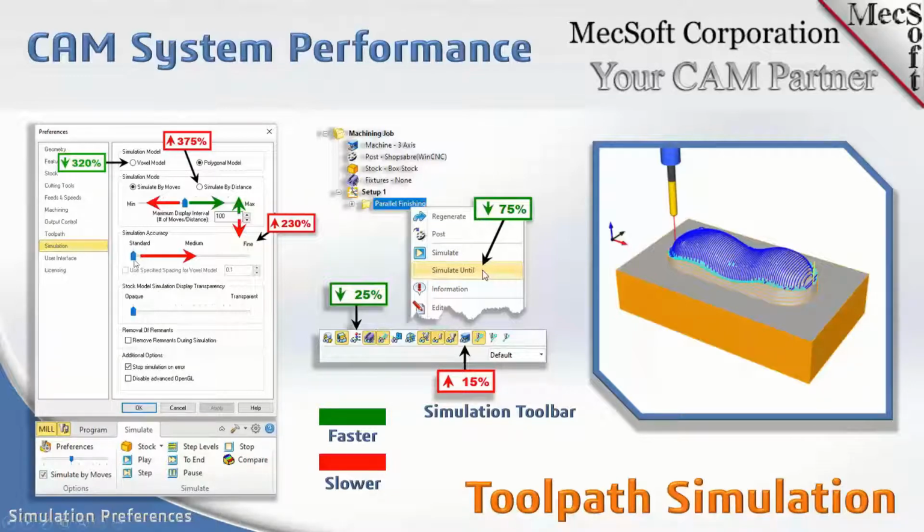Again, there's a slider for accuracy: standard, medium, and fine. Just be cognizant that if you jack it up to the right, you're going to slow down your simulation time. It could be as much as 200 or 300%, 2 or 3 times longer, by using a finer simulation. So if you don't need to, there's no need to.